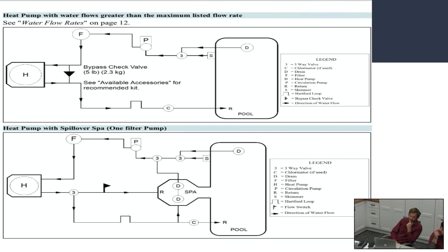And then listed right on the valve itself, if it has the handle, is the direction of on and off. If the valve is missing its handle, there's a little notch. The smallest notch is the off direction. You grab a handle from any of the other valves and walk it over to the one you need to turn, just to confirm its direction. It'll show off, and then the handle's typically pointing towards on. Okay?